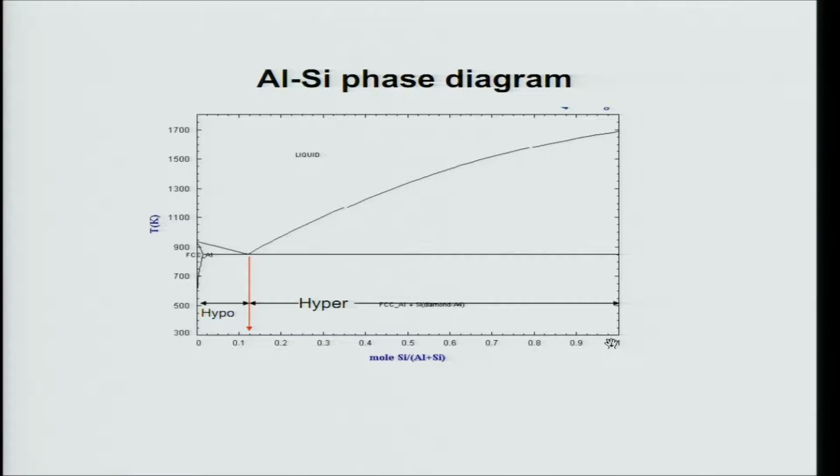That is why it is called alpha. Alpha is the first Greek letter, so the phase diagram starts with that. So alpha aluminum, or you can write aluminum within brackets, is also a solid solution. You can clearly see there is a eutectic reaction here. This is the third type, where only one end has a solid solution and the other end does not have anything. What kind of microstructure forms?